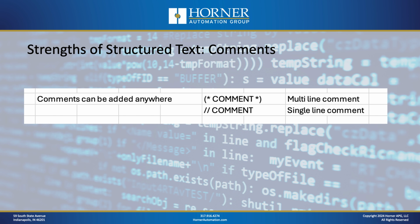Comments can be added anywhere. They can be above your code. They can be to the left of your code, to the right of your code. And that's particularly with the single line comments, but also you can use the multi-line and have what I'll call a paragraph of code and just have one comment for all of it. And you can mix and match and place them wherever you want to. So now you're just not limited to a comment above your rung of logic. Yeah, so no excuses, people. Comment your code.